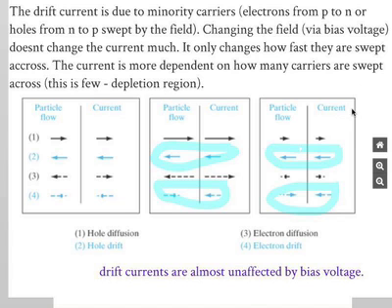So if you look at the reverse bias situation, you will see why this is important. Okay? In the reverse bias situation, you can see the diffusion current is very low. You're basically killing that by increasing the energy barrier. You're decreasing the diffusion of the electrons, diffusion of the holes. So the only thing that survives primarily is the drift current. Is this component, right? It's just sweeping across. And that's the current which shows up here. And that's the problematic current typically.